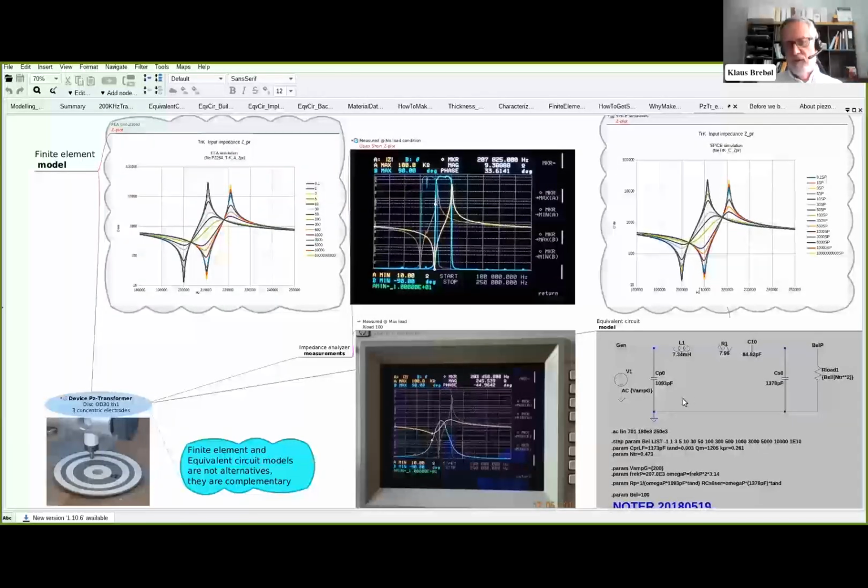And as you can see, when we go from a no load condition, a very high impedance, where we have a high Q resonator, and then with gradually lowering the resistance, we go to a low Q situation here. And again, that's around 100 ohms load. And then when we continue to short circuiting, we end up in a high Q condition again.